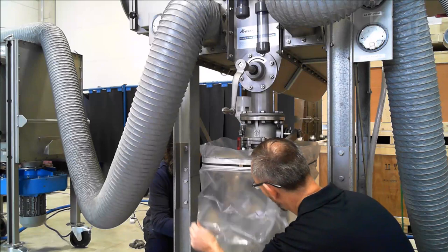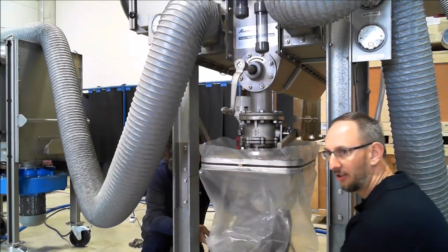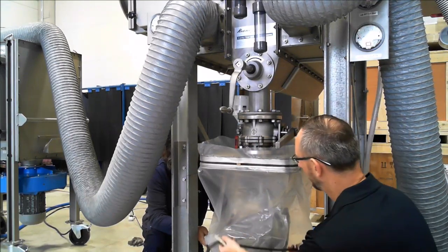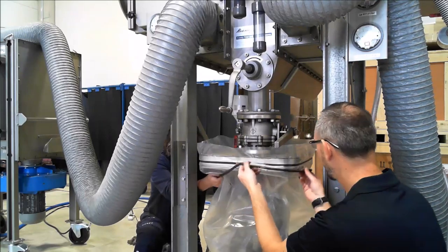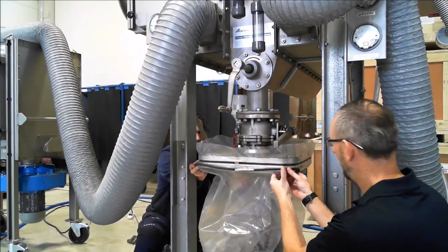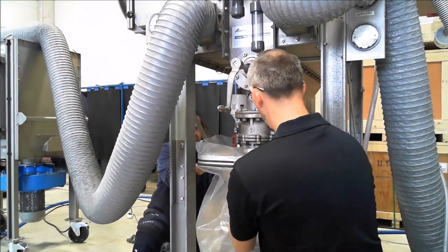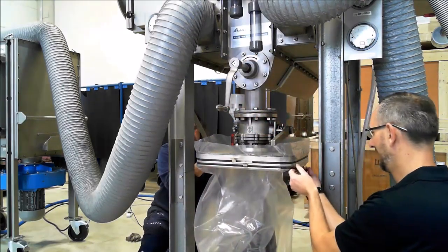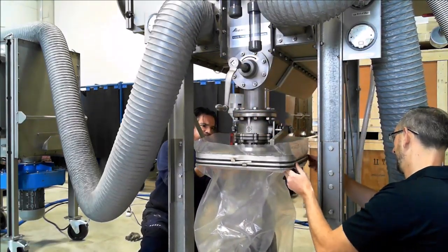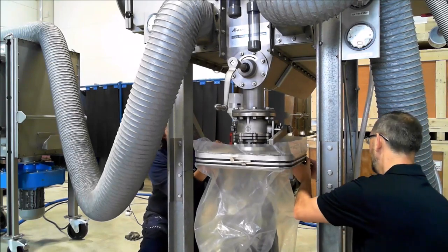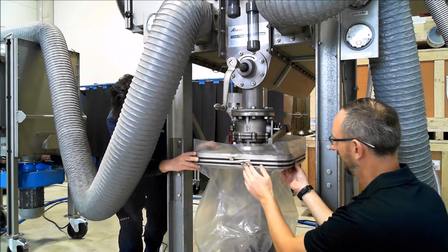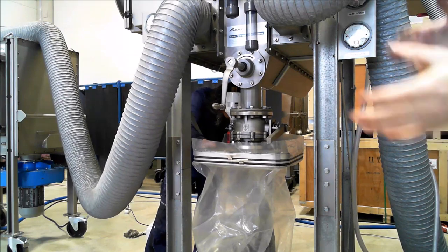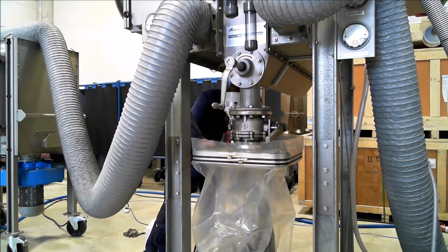So in this case, we have again a new bag. We can place now also a barrel underneath it, and then we can start draining the next barrel. So as the last step, we just fix the second rubber ring. And also here it is important to have the handle in a position where you can easily have access to it. So and now you could continue to drain then the next barrel. And that's the procedure how to fill and how to drain the carbon in our carbon filtration systems.